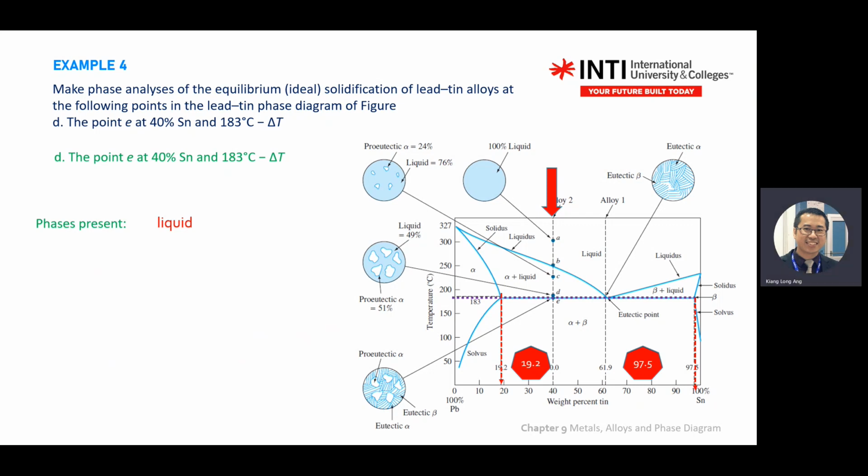Ask yourself what is eutectic. Eutectic is the last drop of liquid that you can see, and then you write the equation. What does eutectic mean? Liquid drops down, cools down, you get solid. So it should not be this eutectic point. It should go to the solid. So you will stop at solid.